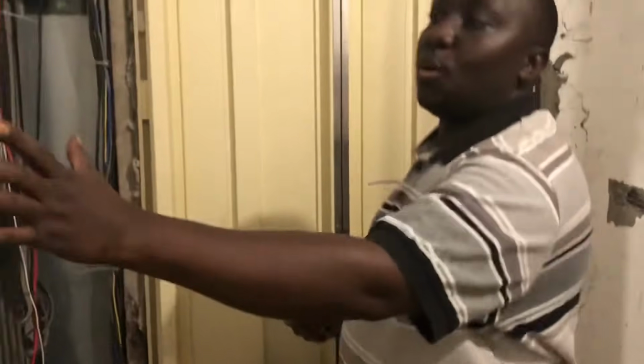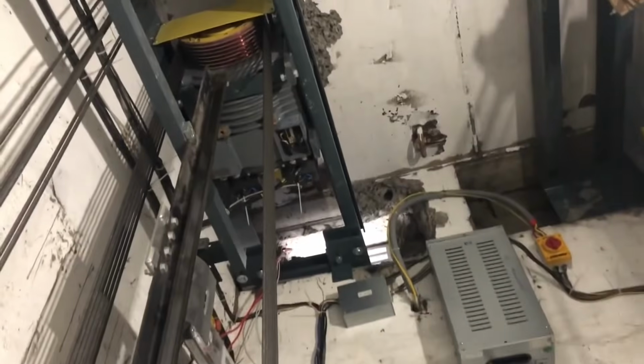We also have these ropes, hoisting ropes. You can see they are from there, coming this way, going to the something we call counterweight, which you will see later when we are going through. Then it comes and the dead end is there. This is we are on top of the elevator, where it is hoisted through ropes.